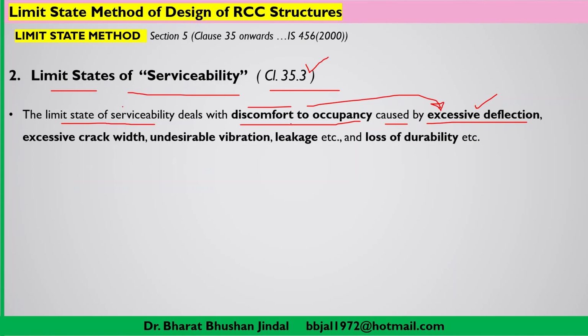So what type of discomfort? It may be due to excessive deflection. There may be excessive crack width. If you find cracks in any type of structure, say a slab, then you will try to move away from the slab because you will be losing confidence. Any undesirable type of vibration, leakage, etc., or loss of durability. So this will be the limit state of serviceability when you feel any type of discomfort.